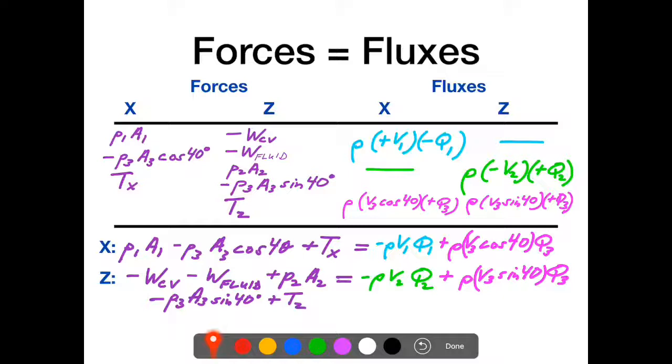And again, depending on what is known or unknown, you can solve for different things. In our problem, we don't know the support force, so we can back that out if we plug everything else in. Other problems, maybe you're solving for a pressure, maybe you're solving for a weight or whatever. It just depends on the particular architecture of the problem. Again, the pressures at control section number 3 for this problem, it's a free jet, so those go away, but I did want you to include them in there to see how they go.